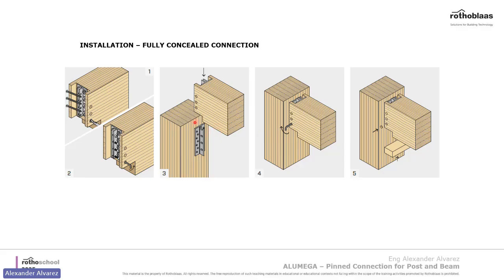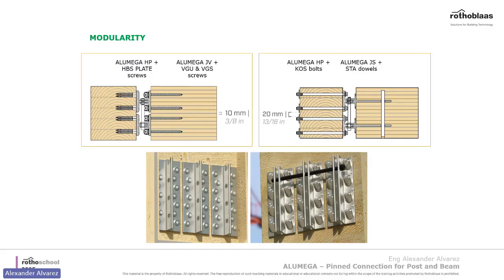But to make sure that you don't see the hangers from the bottom, you can use a wooden block to cover it up, and then just use these wooden caps to cover up the dowels. The reason for this is either for aesthetic reasons, you don't want to see the connectors, but also for the fire rating reason as well. It's able to prevent the fire if there is a fire at the bottom, like on the floor, and you can feel the heat and the fire go up. You have these wooden blocks covering it up. So there's that.